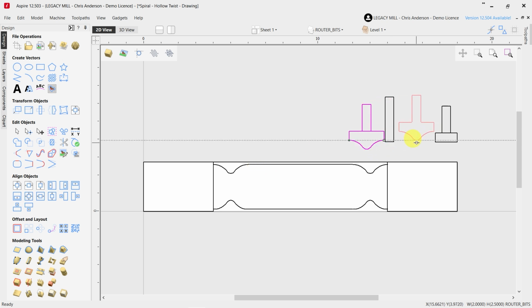After that, a second cutter is going to pierce and hollow the material. This is going to plunge into the blank as well, starting at a position, plunging down, and then traveling down the stock per rotation, matching the same toolpath as what the barley twist did originally. It will then repeat that over and over again until it gets to the very center of our blank, hollowing out that toolpath. It will repeat that process again for as many starts as the barley twist is doing. So it matches it. That way we're hollowing out the center using some form of a piercing cutter.